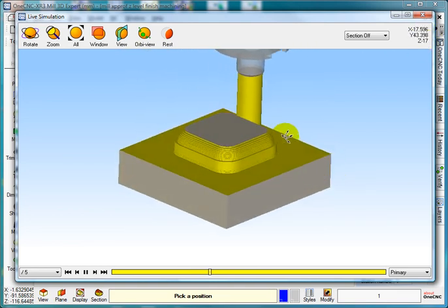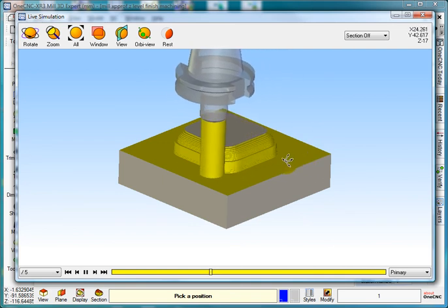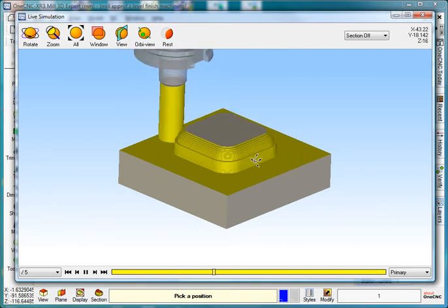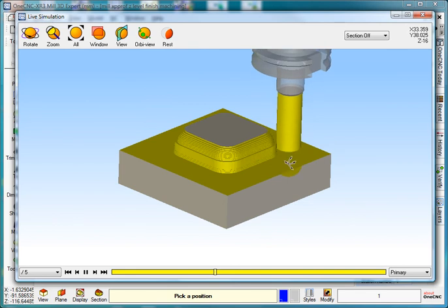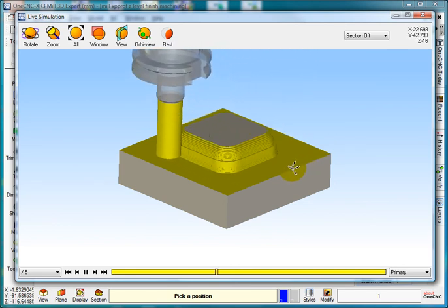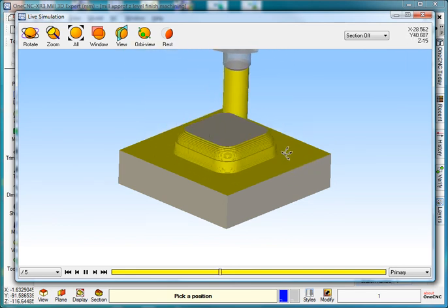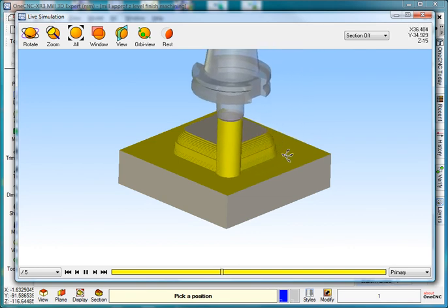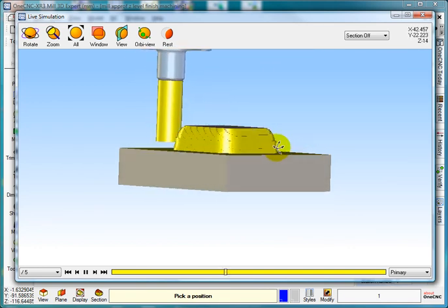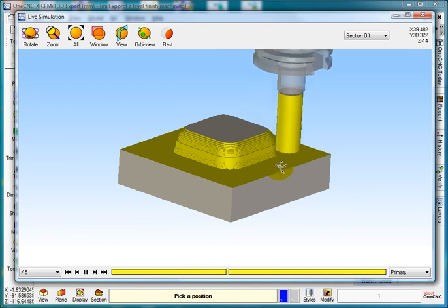So we're actually putting a decent cut on, and then what we're getting is we're getting the cutter to work for us as well, because normally when we rough out, we normally can only go 2 or 3mm at a time. Well, this is using most of the flute of the cutter to semi-finish with, because it's just coming up in 1mm steps.